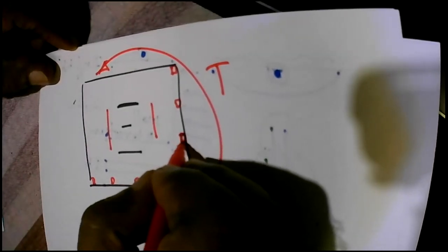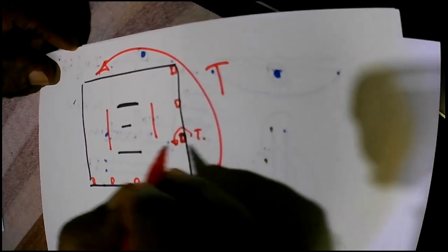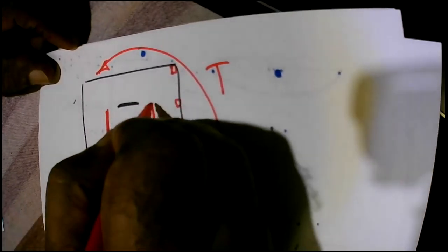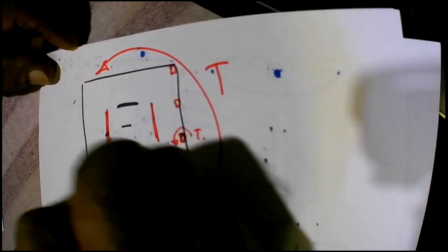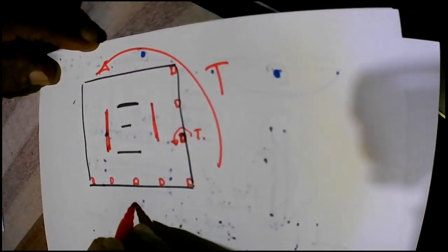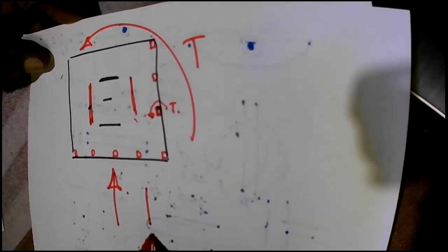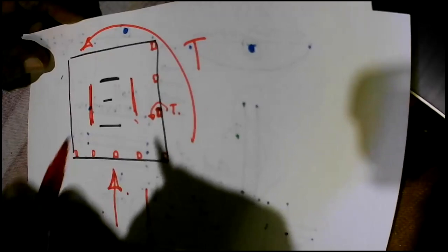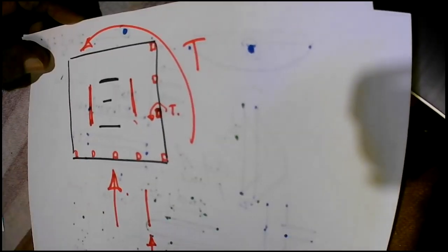then what happens is these columns will not be subjected to a torsional moment because the twisting is controlled by these elements. The shear walls are controlling the twisting. So due to twisting moment, this shear wall, so twisting this way occurs due to wind load this way. So due to this wind load, this particular shear wall will be subjected to a load this way. And in addition to this, we have a twisting moment. Due to twisting moment also, there will be another load this way.